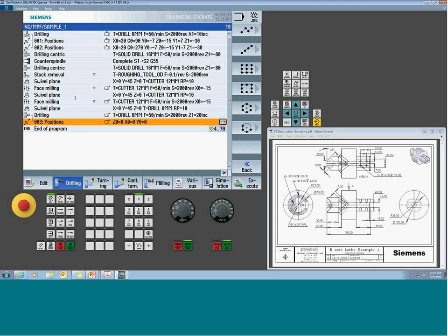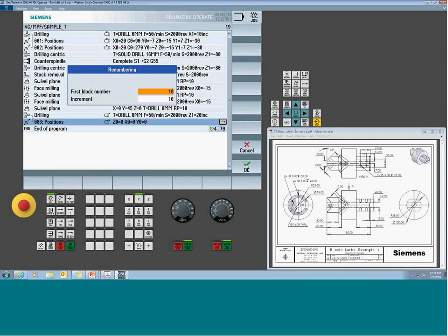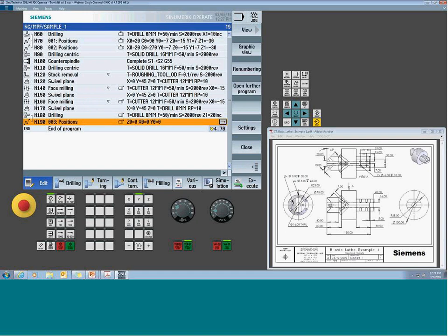Now, when we start to get to some of those repetitious events, sometimes it's nice to not have to keep copying and pasting and maintaining the same geometry in multiple lengths. That's an area where I like to use the repeat command. Now, with the repeat command, you can use all kinds of different markers to tell it where to go. Probably the easiest thing to do is to go to your edit function, go to the numbering option, and give yourself some N numbers. Plug in some N numbers, and I have some automatic point locations.